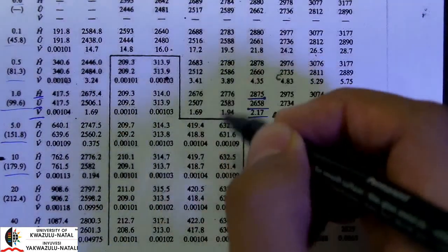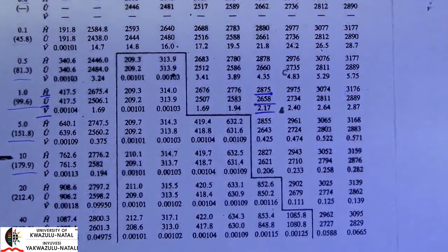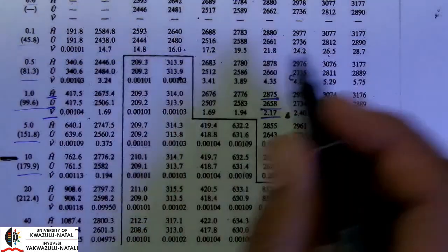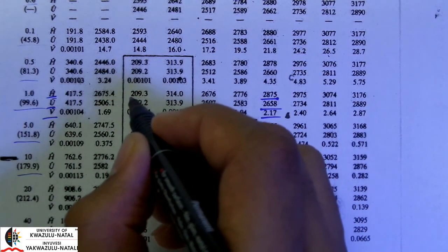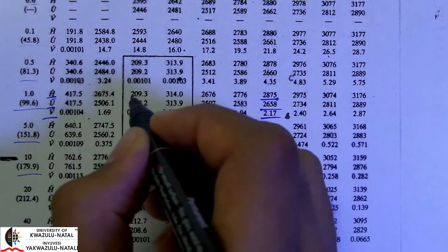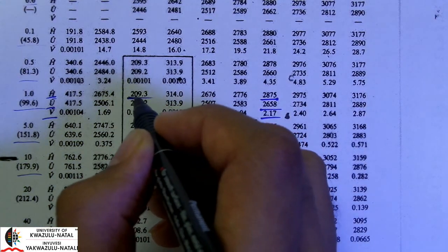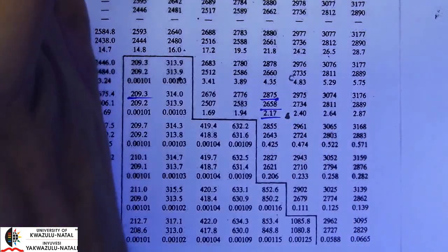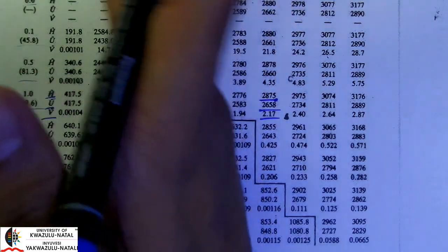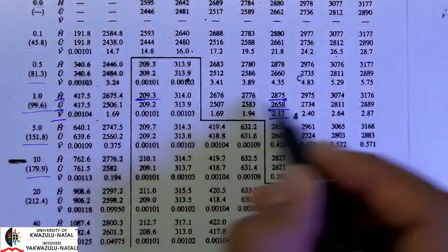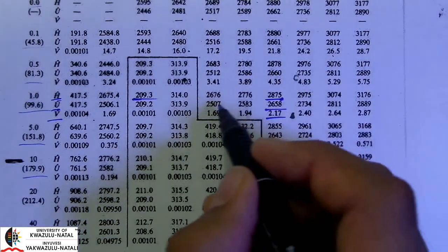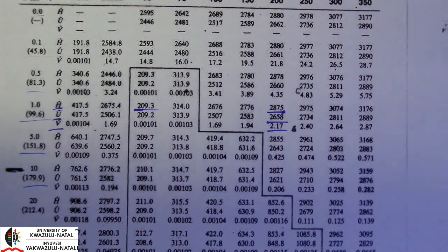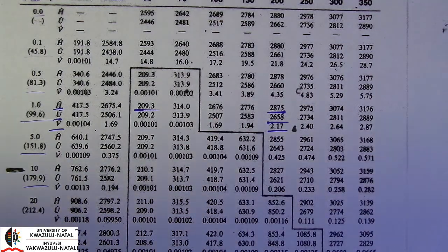And one important thing to note is that this diagram takes into account our latent heat of vaporization. So if I were heating a liquid, for example, from 50 degrees to 200 degrees, I can simply note the difference in my enthalpies. So we don't have to look at dividing into sensible heat, latent heat, and sensible heat again. The sensible heat is already included in our difference. And that's the advantage of using our steam tables if they are available.